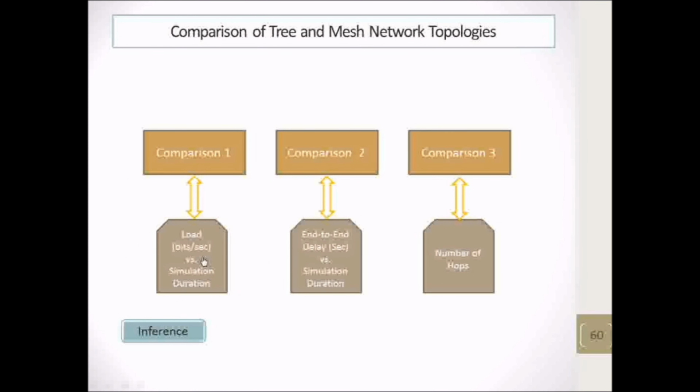The read buffer stores the value that is fetched, and this is the string subset block. It reads the returned special character. There will be 4 bytes. The first byte, that is the 0th byte, will correspond to the special character, and the next 3 bytes will correspond to the value associated with that special character. Suppose in the 4 bytes the first byte is star, then the system understands that the values returned are associated with the temperature sensor, and the next 3 values are the temperature values.